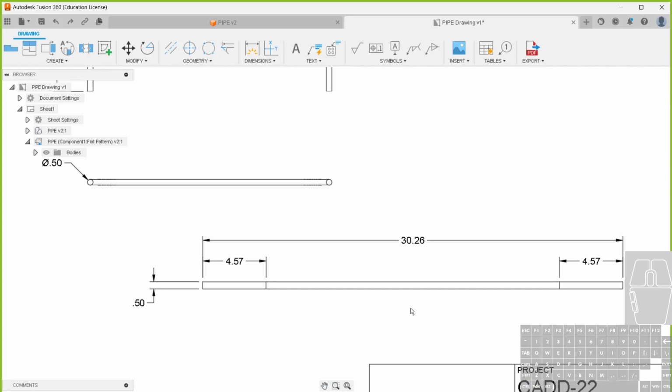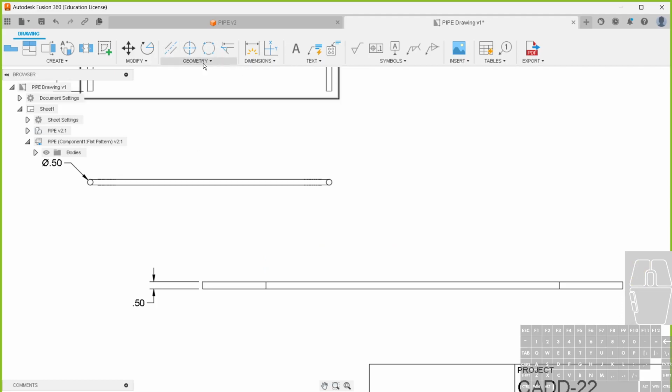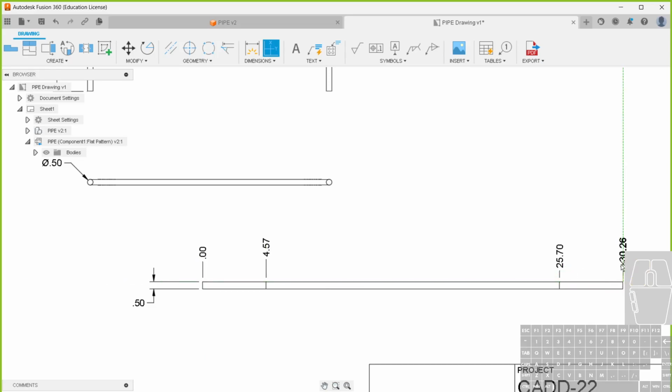It's nice on a sheet metal to kind of show all the bends. A lot of times on sheet metal, I'll even do ordinate dimensioning. So doing this one right here, ordinate, where I can call it a 0, and I can just call out how far it is from that point. Because it takes up less space, especially if you have a lot of bends, like you mentioned this had like 7 bends on it. If I was using baseline, which is the other way, that dimension would be way out here, right? But in ordinate, they all stay real close.